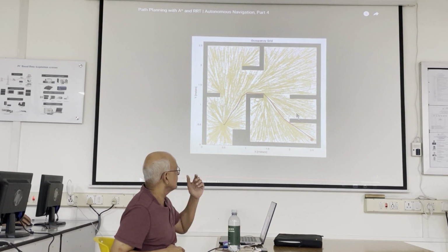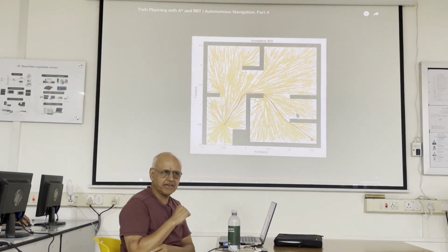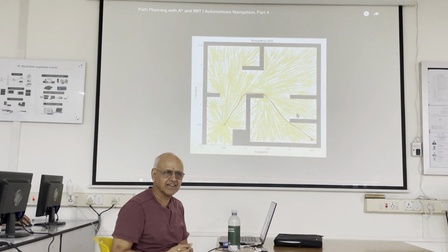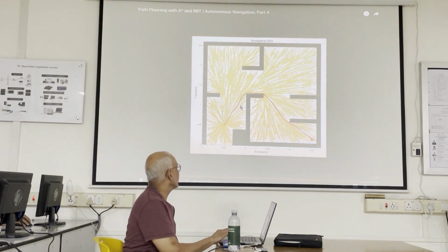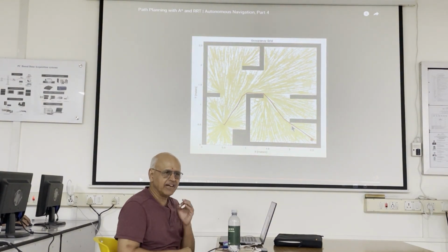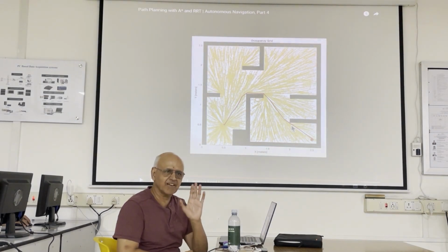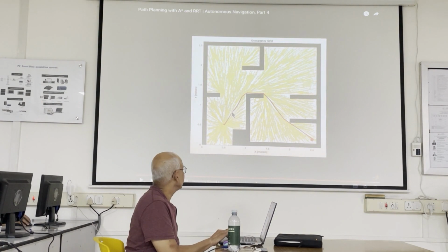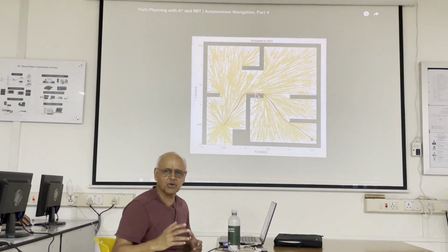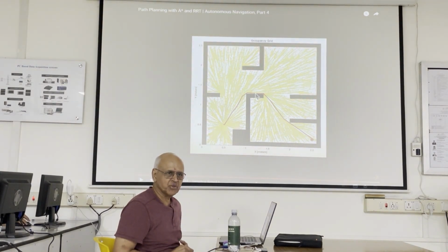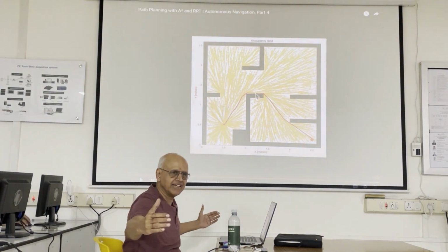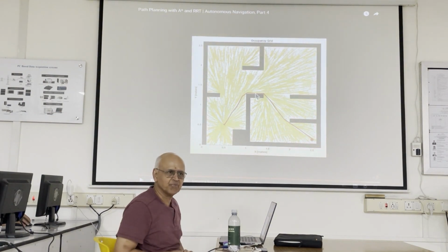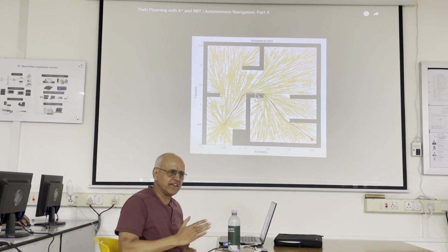The other thing I'm going to point out is that the kinematics and dynamics, for a long time I was wondering how do they do trajectory planning, right? Because he kept talking about path planning, but they're not talking about how to take a vehicle through that. Apparently these RRT paths are refined enough so that you can let the vehicle navigate the corner point. So basically you'll find enough curvature here and here so that most robots will be able to go through without having a problem. So it turns out that you don't need that trajectory planning aspect most of the time. Sometimes you may, if you have a long 18-wheel truck, then it's a different issue. But for most cars, it can navigate this path.